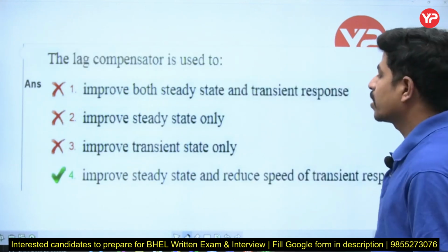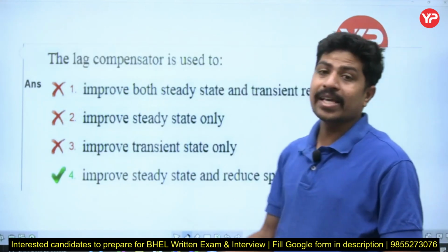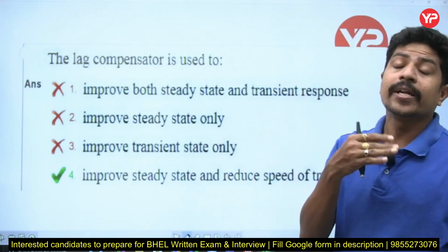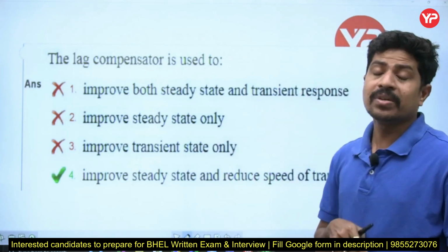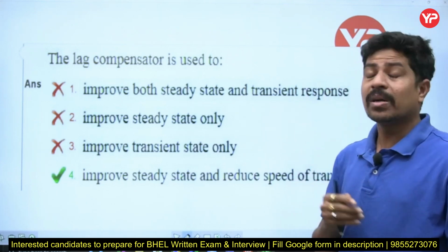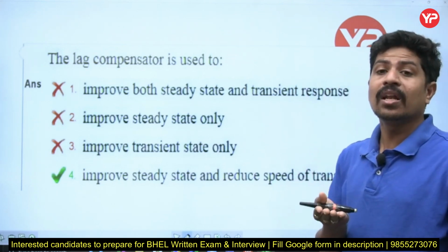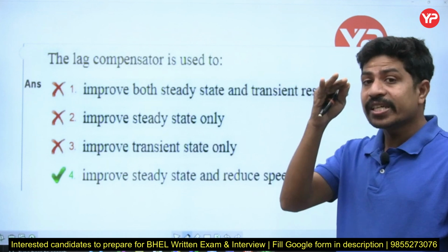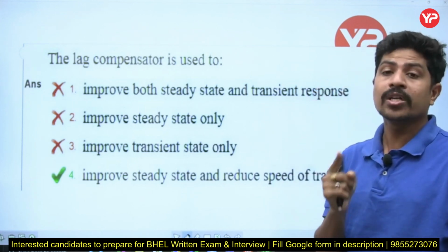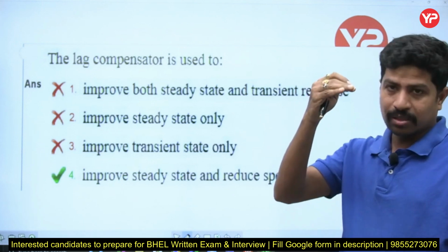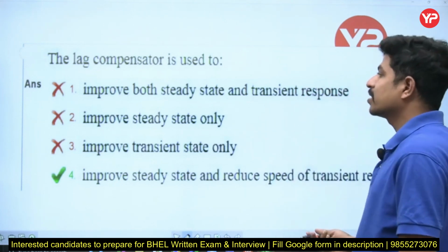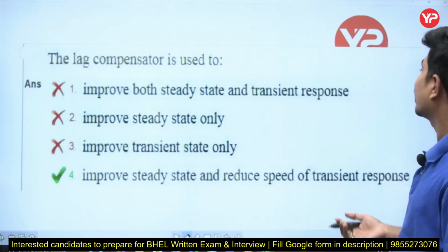The lag compensator is used. Yes, lag is similar to PI controller. It improves stability, lag compensator. PI will decrease the stability. PI will decrease steady state error, but stability is decreased. PD will improve the stability, PD will decrease the time response, but PD is not going to reduce the steady state error. If I combine these two, PD and PI, all the requirements can be achieved. So the answer is improve both steady state and transient response.